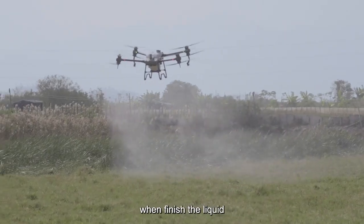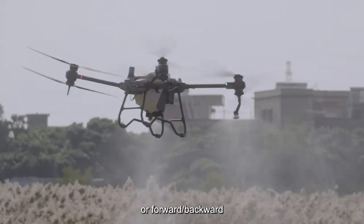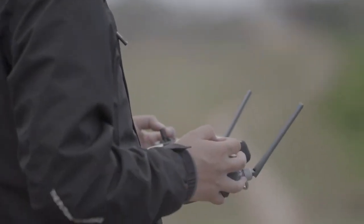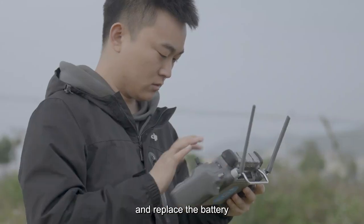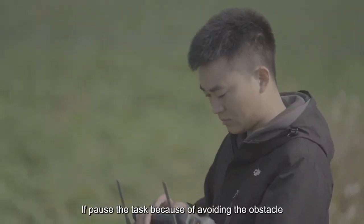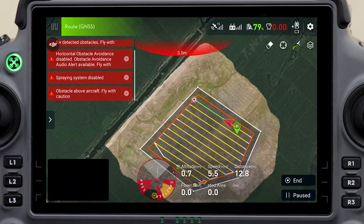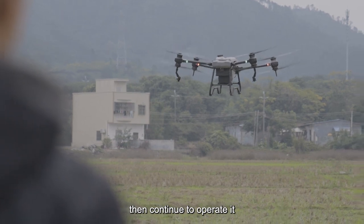During spraying, when the liquid runs out or you manually move the aircraft left/right or forward/backward, the task will be paused. When the liquid is finished, operate the agricultural drone to return, refill the liquid and replace the battery, and then resume the operation. If you pause the task to avoid an obstacle, select the return point based on the prompt on the screen. If you recall the aircraft to the refilling point, adjust its orientation and ensure the pilot faces the rear of the aircraft, then continue to operate it.